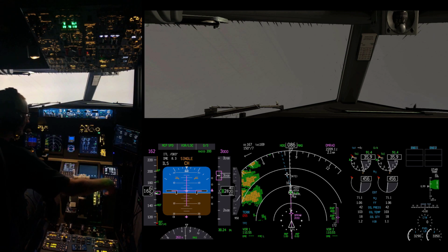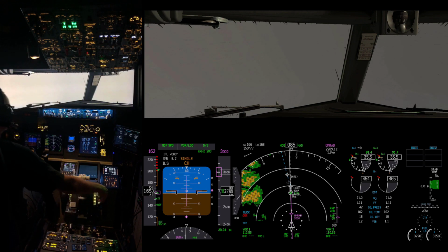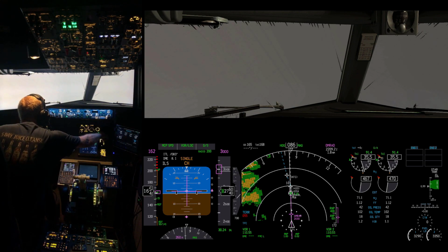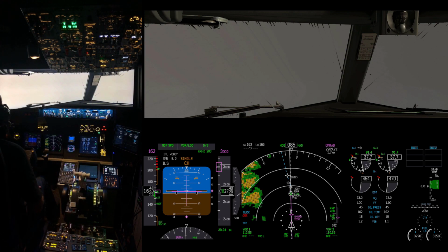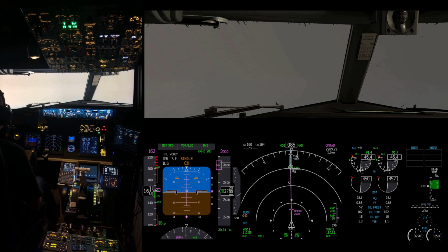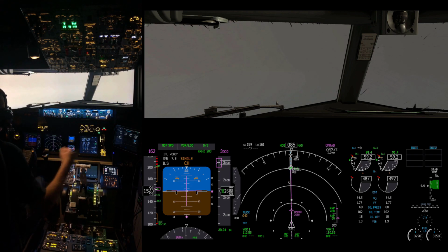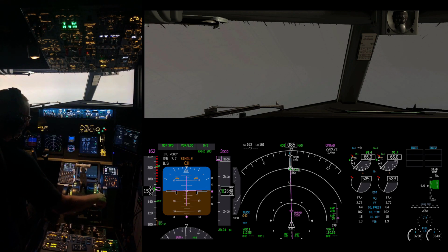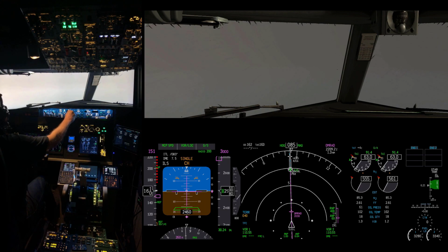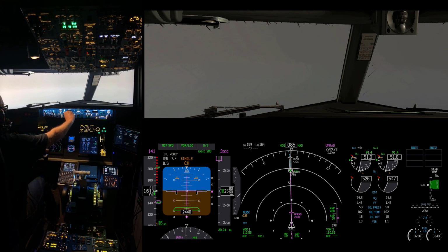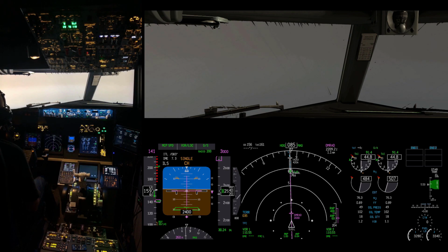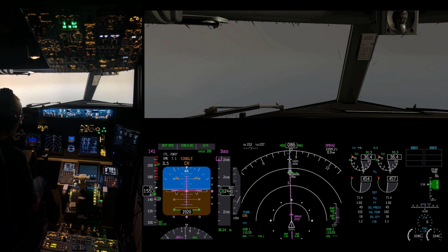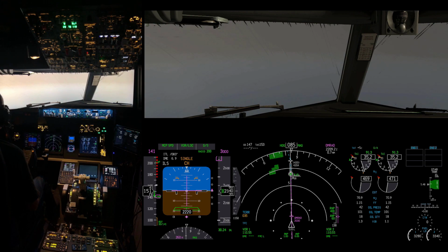So now we'll configure for landing. Flaps 15. Gear down. And we have flaps 30. And indicated airspeed, we referenced 141, so that's set. And the aircraft is trimming in order to match the appropriate glide slope angle. Ready to descend. And we still can't see the airport.